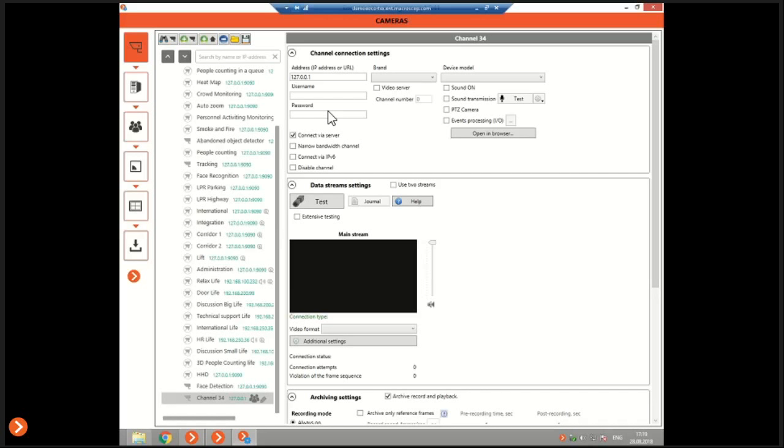One thing that I want to say about this software is that if you're going to use Eocortex, it is better to disable the firewall and also the antiviruses, because these software can create a conflict with the data that is transferred from cameras to servers and from servers to client.